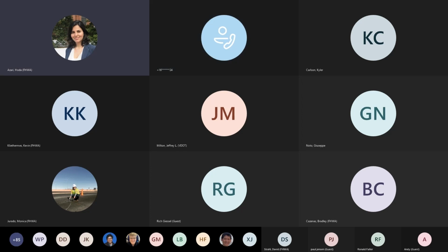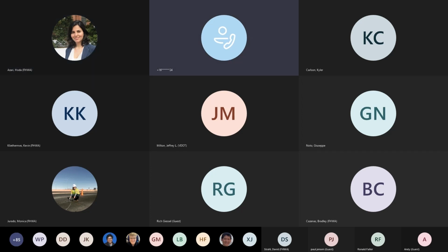I believe so, yes. We've done some work in this area, and it's certainly done by individual members, but that's more into production of components in the manufacturing facility. You can assign properties very effectively using modal. In a bridge, though, it's quite different, and you can get a system response, and you can use it to indicate problems in a bridge, not necessarily identifying the problem area, but you can detect there's a problem, like say an entire girder out of a multi-girder system is distressed or failed.